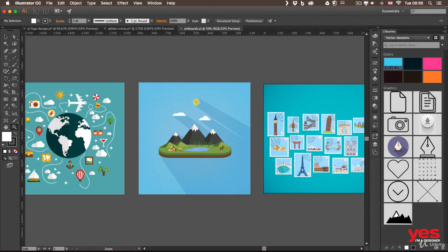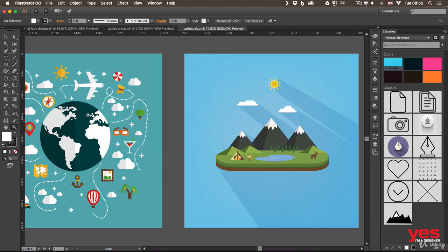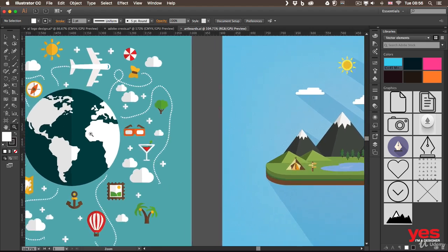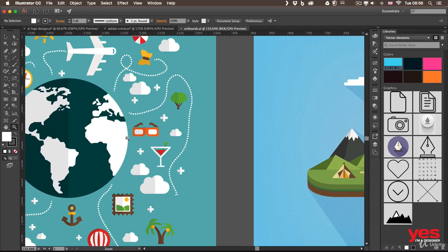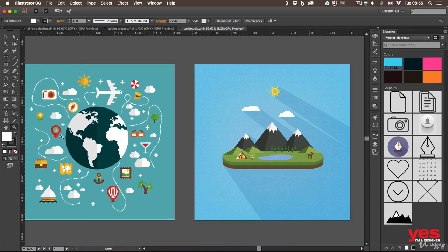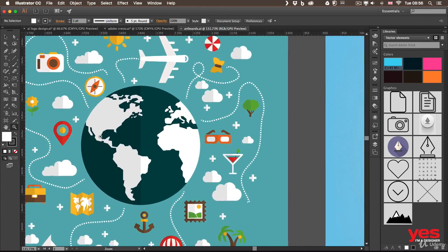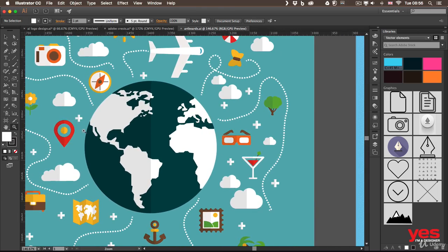Once the zoom tool is selected, you will be able to zoom in two different ways. If you have a faster computer and a good graphic processor, you will be able to use the animated zoom, which means you can just click and drag to the right to zoom in and drag to the left to zoom out. Now this tool actually zooms to wherever you click. So it tries to center to that area.